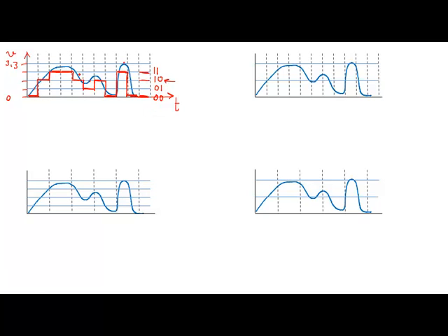Now, if you look at the digital signal, the resolution in time is called the sampling time. So your sampling time, if I assume every dashed line is 1 microsecond, is going to be 1 microsecond, one sample per microsecond, or 1 megahertz sampling. And if you look at the levels of the value that you have, this is called the A to D resolution, or the value resolution, right?